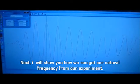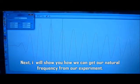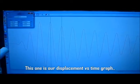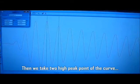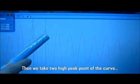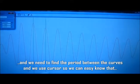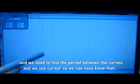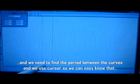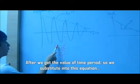Next, I will show you how we can get our natural frequency from our experiment. This one is our displacement versus time graph. Then we take two high peak points of the curve, and we need to find the period between them, and we use the cursors. Then we can easily know that the time period is 0.9 seconds.